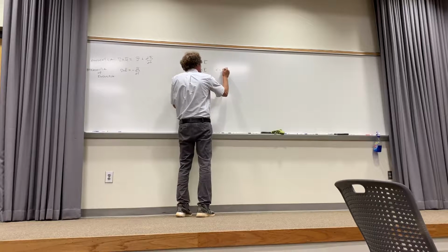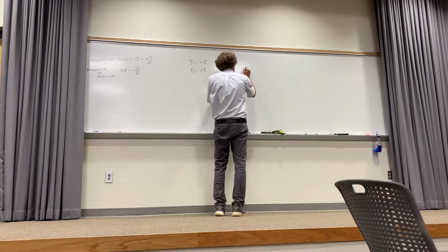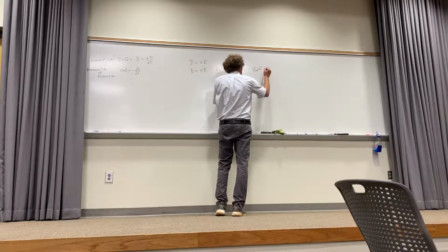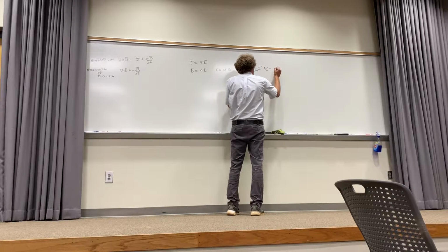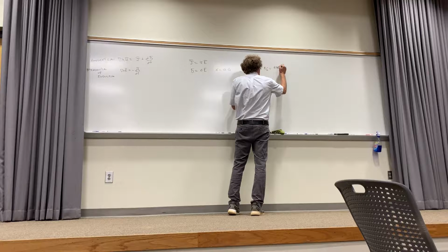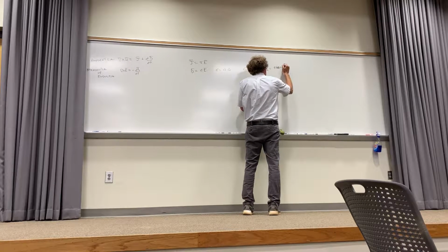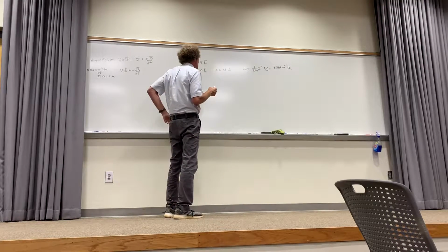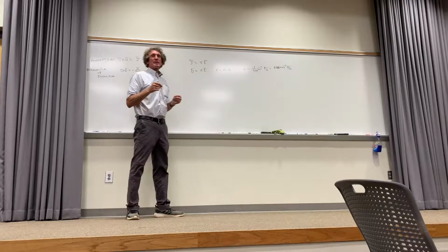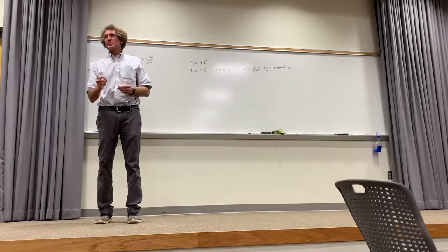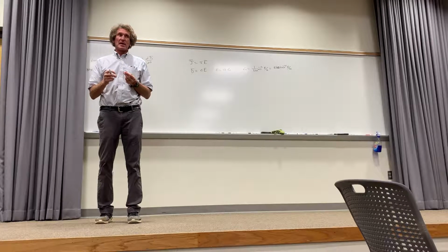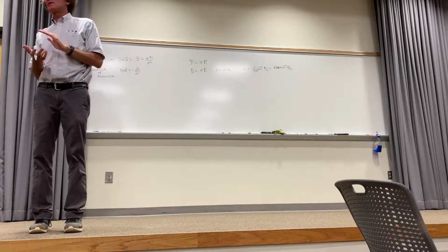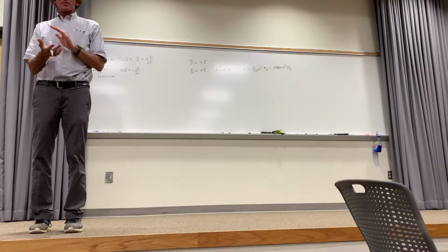Here, epsilon is epsilon relative times epsilon naught, and epsilon naught is 1 over 36 pi times 10 to the minus 9 farads per meter, or 8.854, this is an approximation, times 10 to the minus 12 farads per meter. We use this a lot because it makes calculations easy by cancellation. And epsilon relative just gives us an idea of how much more energy that material can store than free space. Remember when you added a dielectric, in electrostatics, a dielectric with a higher permittivity for a given voltage, you could store more energy. Do you all remember this class?